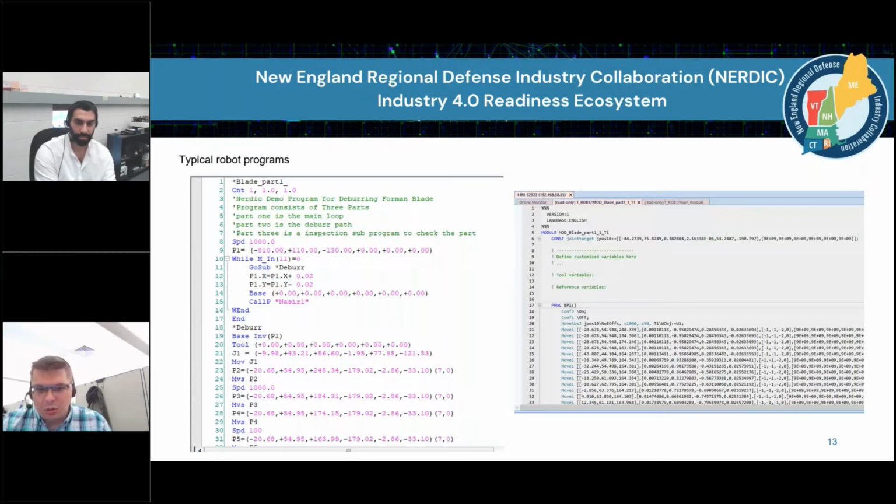And if you're very familiar with robot programming and coding of industrial robots, you can skip the graphical front end and go directly to this back end code and write and manipulate the code and information just like you would a traditional industrial robot. So that's why I said that the last point on the disadvantages to cobots, it very much depends on the brand and type of cobot that you get as to how much it will support the more feature-rich back-end code that the standard industrial robots work with.